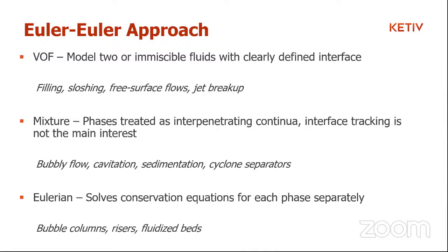In the VOF model, which is the volume of fluid model, what we are interested in is being able to track the boundary between two or more different phases. This boundary, this interface, is of interest to us. For example, if you were doing a free surface flow wherein you have a riverbank and you're modeling the waves, for example the shape of the waves, then you would choose a VOF model.